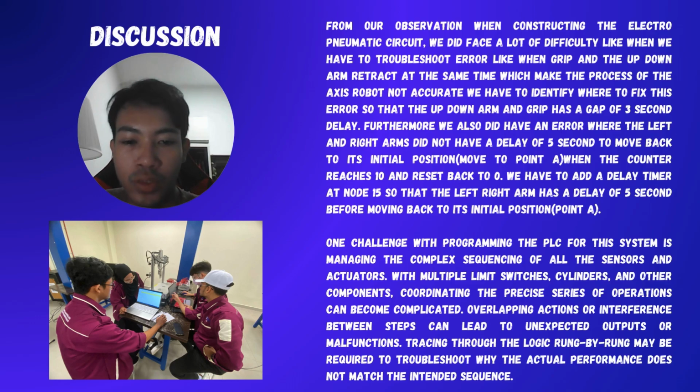Okay, for the PLC, one challenge with programming the PLC for the system is managing the complex sequencing of all the sensors and actuators with multiple limit switches, cylinders, and other components. Coordinating the precise series of operations can become complicated. Overlapping actions or interference between steps can lead to unexpected output or malfunction. Tracing through the logic rung by rung may be required to troubleshoot when the actual performance does not match the intended sequence. Okay, that's all for the discussion.